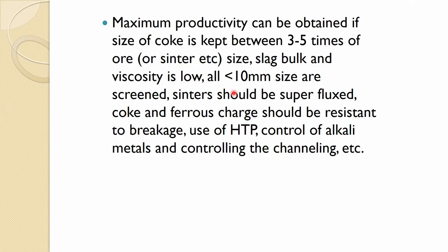So, maximum productivity can be obtained if the size of coke is kept between 3 to 5 times the ore size. Usually sinters can do that, and many of the modern blast furnaces operate with almost 80, 90 or sometimes even 100% sinter or pellet.